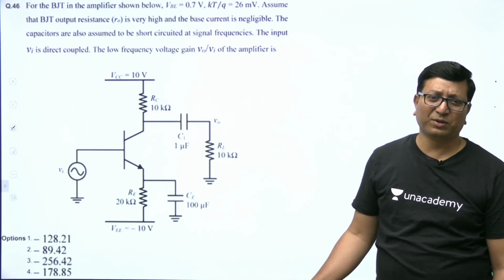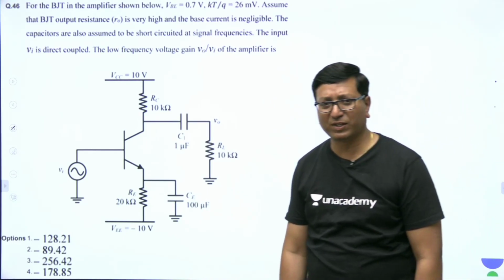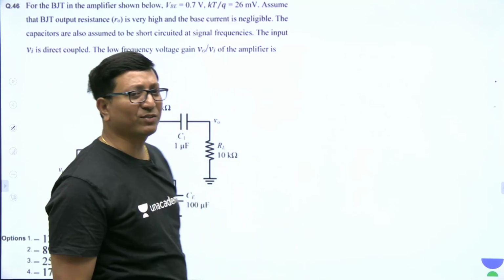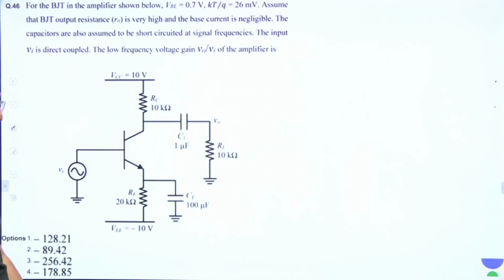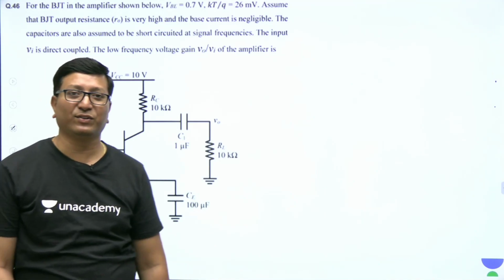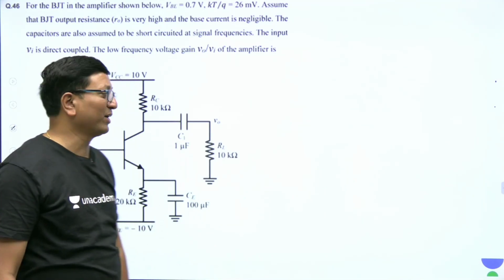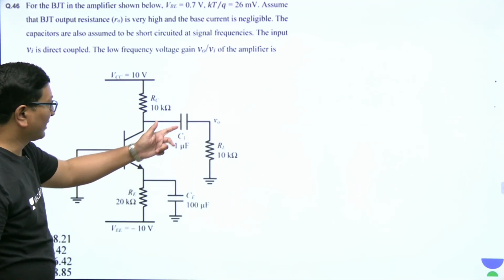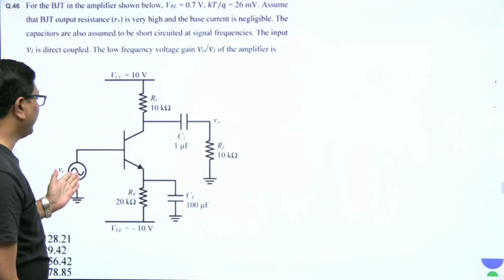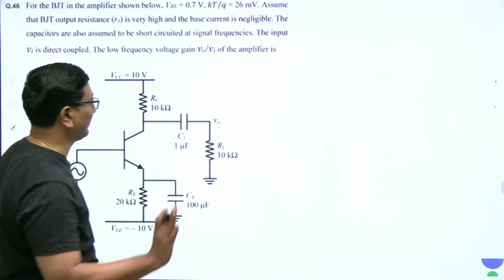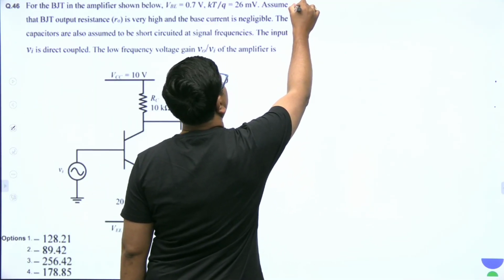Always, right? So how many times we did this kind of problems, right? Once we start amplifiers, this is a very basic circuit, right? We deal with, of course. So as far as the circuit is concerned, first let us have a look at its DC equivalent circuit. With respect to DC, what do we get? All the capacitors act as open circuit and the AC source is removed, but it is not superposition, right?